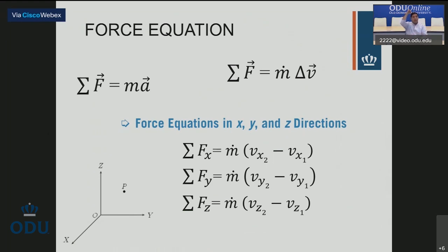Now, if you are in Illinois, then your coordinate system is somewhere else, meaning that the distance from that coordinate system to my point here in Norfolk is different from the one I have. So every time you deal with this type of thing, you must tell your client, or the person you're giving the results to, where your coordinate system is located.